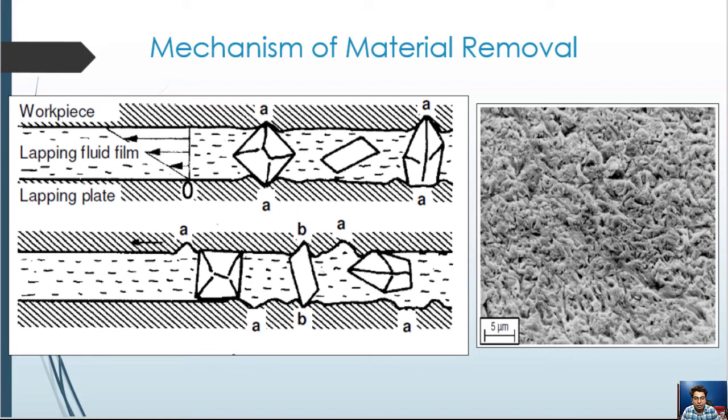Material removal occurs as a result of the effect of the grain rolling on the contact zone between workpiece and the machining disc surface, or grains temporarily fixed in the disc surface. The edges of the lapping grain insert themselves into the working material. The depth of insertion depends on the surface strain and material, usually between 5 to 10% of average grain diameter. Through the vortex developing in the fluid film, the lapping grains straighten themselves out and become engaged.